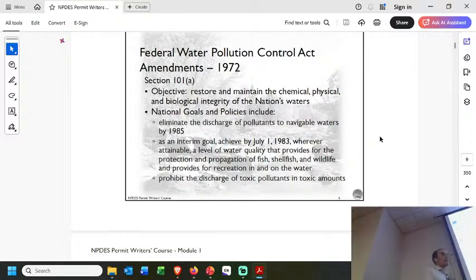But it also doesn't mean we can't have some disruption if we decide that we really would like to have some industry and maybe it's going to discharge just a little bit of BOD, and we can treat it so that it's not a lot of BOD, and we can regulate it so that it's not going to significantly alter the receiving water, okay. We can maintain the biological integrity, right? We're not going to cause an algae bloom. We're not going to cause eutrophication or complete starvation of oxygen. We can maintain that integrity. And we need the physical and chemical as well, because things like pH, which would then affect biological, or simply just changing the entire waterway by adding a bunch of sand, right? That would also just be disruptive.